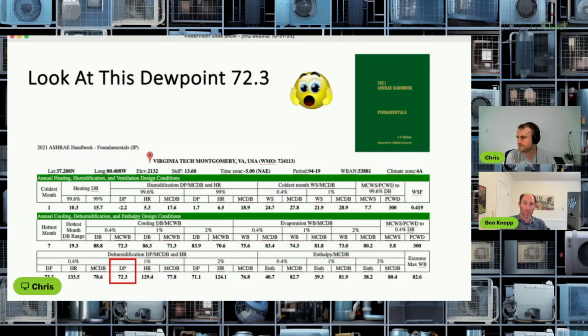And this goes back to, Ben, why we selected the 2-ton, and when Ben was talking about minimum capacity. So the inverter we chose has an established minimum capacity, which I think was 13,000 BTUs. So essentially what we're trying to do is get that system to run as much as we can. Basically we want it to run through the dehumidification dew point days if we can. But to be honest, it's probably not, right? It can only do so much. Yeah, that was the thing.